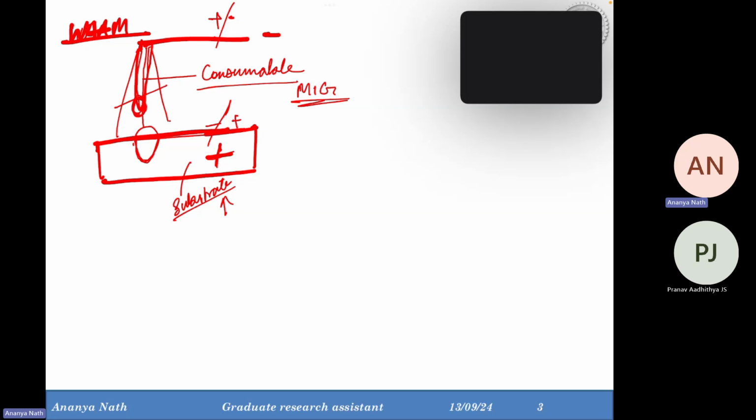So this part of the electrode is melted, and now it is deposited over the weld plate. But in WAAM process, we want the electrode to be deposited over the build plate. But if we are getting very high penetration inside the substrate with each layer, what will happen?